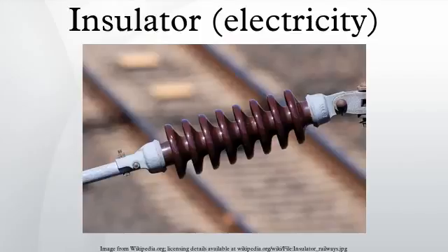Insulation in electrical apparatus: the most important insulation material is air. A variety of solid, liquid, and gaseous insulators are also used in electrical apparatus. In smaller transformers, generators, and electric motors, insulation on the wire coils consists of up to 4 thin layers of polymer varnish film. Film-insulated magnet wire permits a manufacturer to obtain the maximum number of turns within the available space.